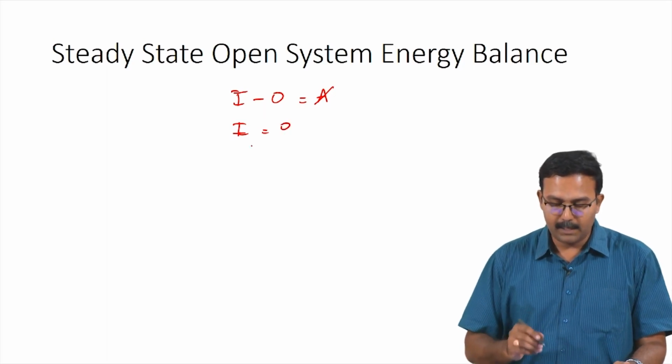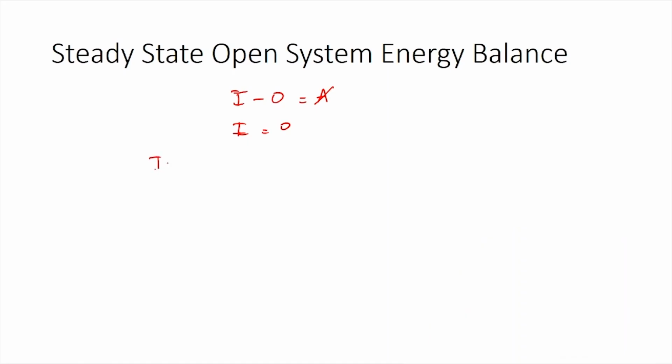So, let us start writing the balance equations for this. Energy which is fed to the system, the input, would be sigma of input of Ej dot, where E is the total energy possessed by a component j, and summation of all the energies of different components will give you the total energy of the input stream. In addition to this, you would also have Q dot, which is the heat which is supplied to the system. So, this would be a positive term.